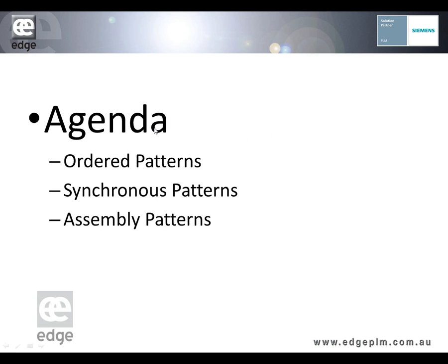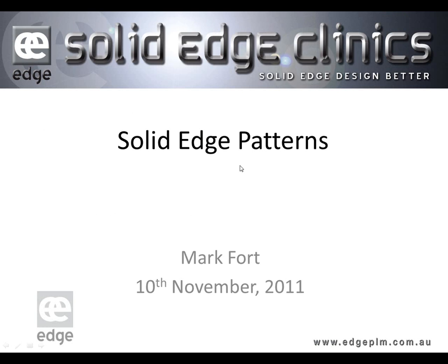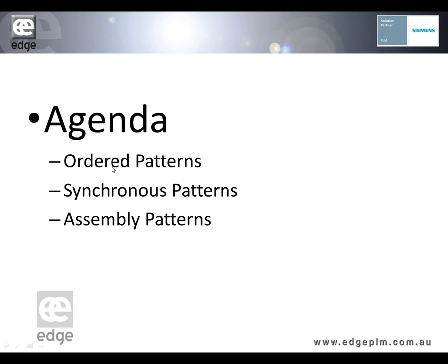Good morning, good afternoon, everybody. Today we're going to be talking about Solid Edge patterns. We'll be talking about patterning in the ordered environment as well as the synchronous environment, and then finally talking about assembly patterns. Patterns are about replicating in the part environment, and these two are replicating features within the part. In assemblies, it's a different procedure. What we're doing is we're replicating not features, but actual parts or groups of parts within the assembly.